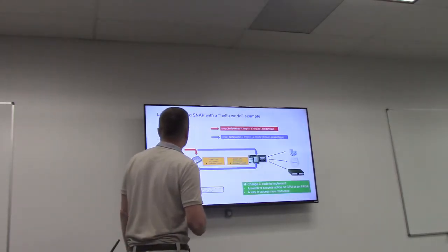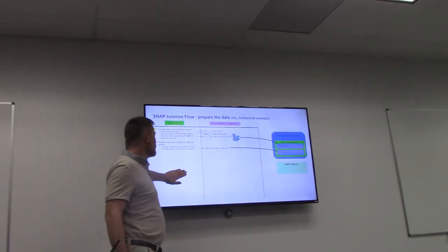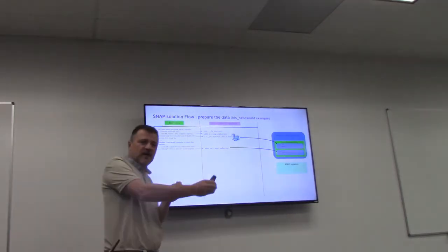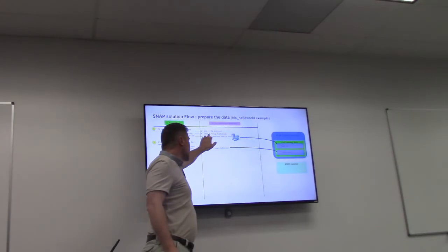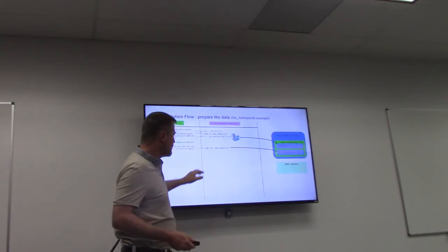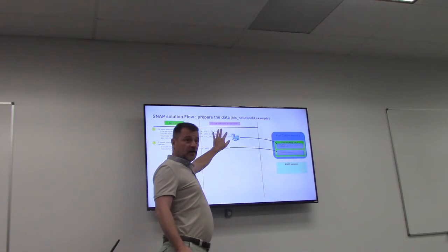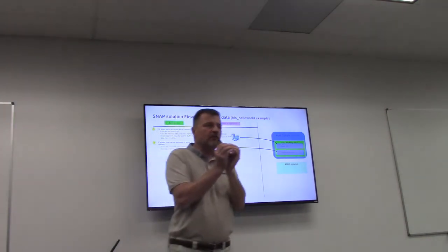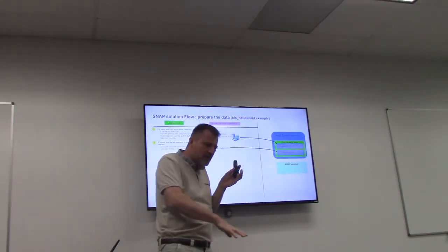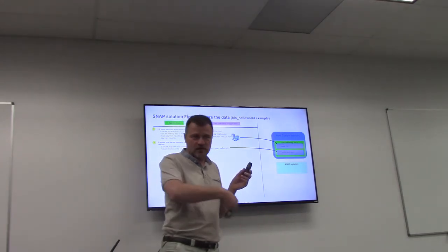Okay. So from the beginning, this is the application. So your main application will submit a specification to the FPGA. We need to define the address in and the address out. That's the minimum. We have a small structure that will be known by these two sides, and we want to limit the number of information we exchange because it goes through a very small, very low bandwidth MMIO channel. Okay.